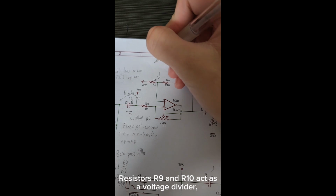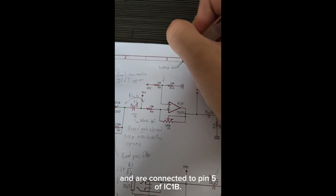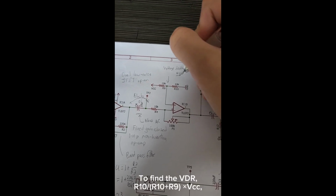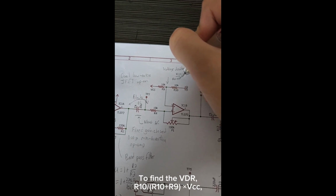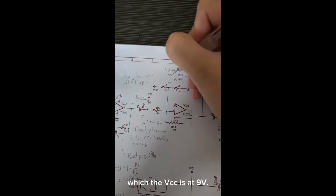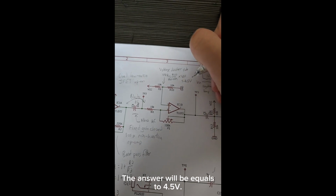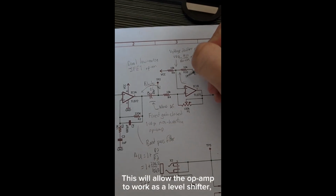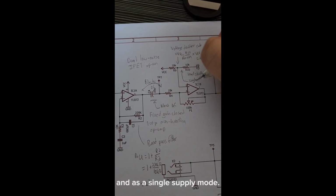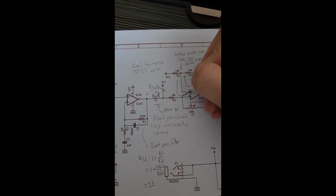Resistors R9 and R10 act as a voltage divider, each at 10k ohms, and are connected to pin 5 of IC1B. To find the VDR, it is equal to R10 over R10 plus R9 times VCC, where VCC is at 9 volts. The answer will be equal to 4.5 volts. This will allow the operational amplifier to work as a level shifter and in single supply mode. This will allow the output to not be saturated.